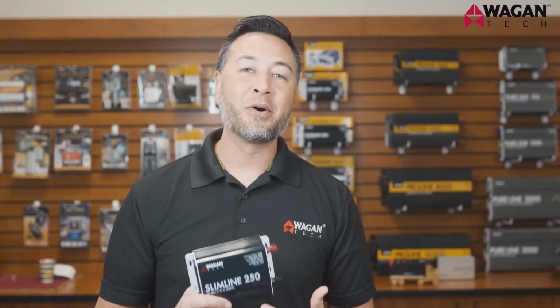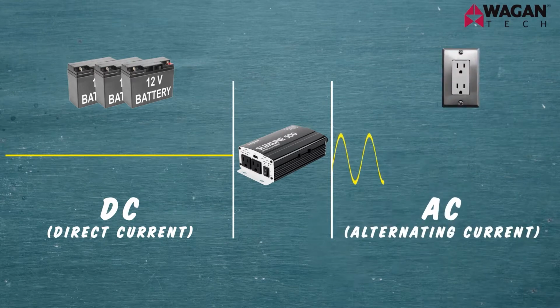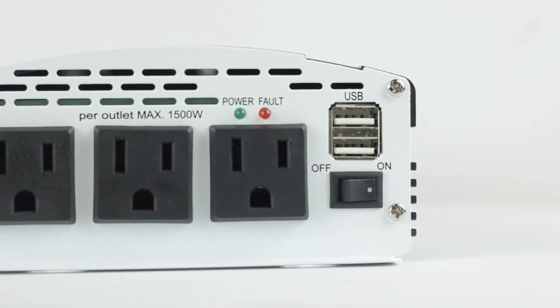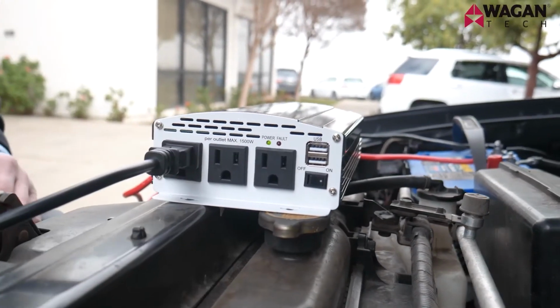First, let's take a look at what a power inverter is. It takes DC current, which is the battery power from your car, and turns it into AC current, which is like what you find in the wall outlet of your house. Power inverters come in two main categories: your standard plug-and-play models, which you simply plug into the 12-volt DC accessory outlet of your car, and the hardwired model. These ones require you to run a positive and a negative power cable to your vehicle's battery.